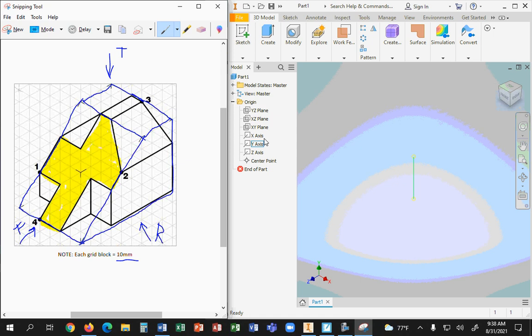Next, when you look at finding your place to land on, the first thing you need are your planes. That's how every parametric product works. It's not unique to Inventor. So when you look at your origin, you're looking to assess your different planes. See that? These are your planes. You want to turn them on, or you can leave them off. When you do this professionally, you might never turn these on, because when you touch it, it activates. See that? When you put your mouse over a plane, it activates.